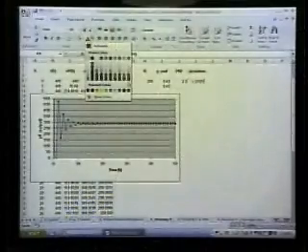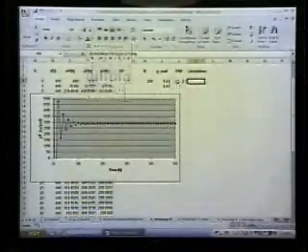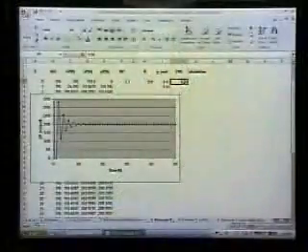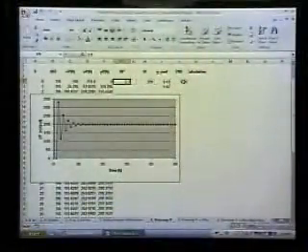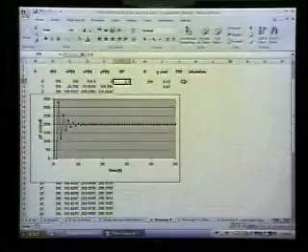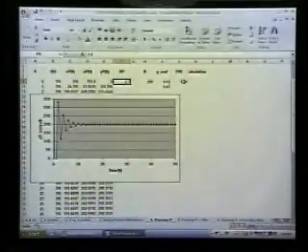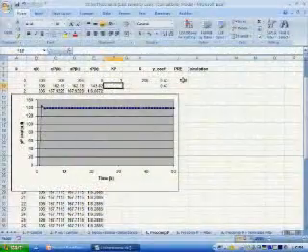It's the magic number. So if we put in 1.52 over here, or 1.53, I think it's closer to it because it was rounding, right? So then I'm pretty good. Now, if I decide, well, I really don't like the way it settles and there's a lot of overshoot, I'm going to change the gain. So I'm going to change the gain to 1.